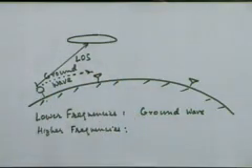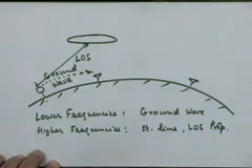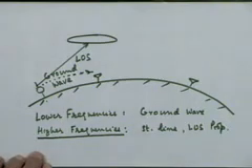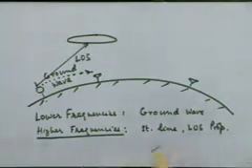Let's say if you have two high towers on the surface of the earth and they can see each other, so line of sight is possible. A straight line propagation is possible at a higher frequency, right? So we call straight line or LOS propagation is possible. Now if you want to work at a higher frequency, there is then a limitation as to how much distance you can communicate, because the propagation will have to be a straight line, a line of sight propagation, and because of the earth's curvature there is a certain distance beyond which you will not see, right?